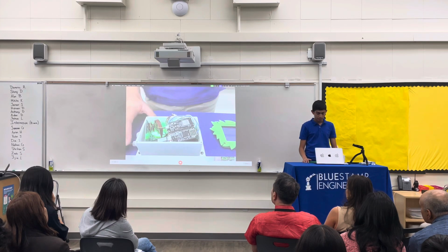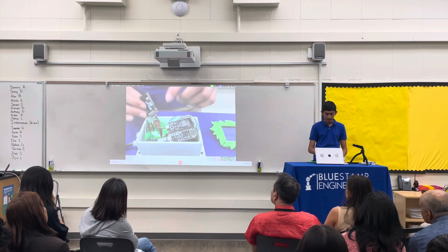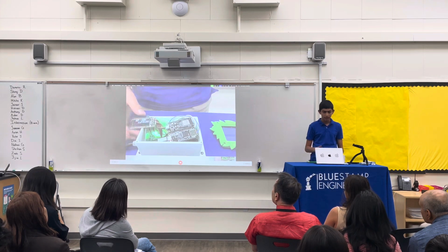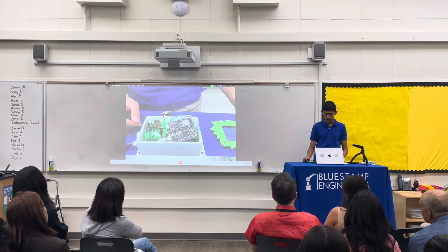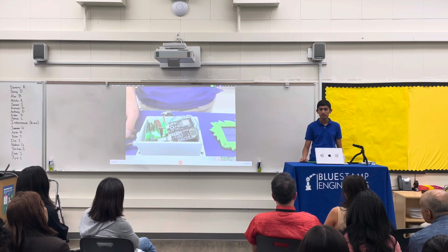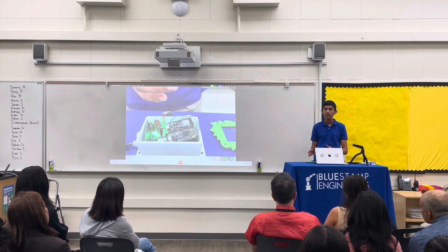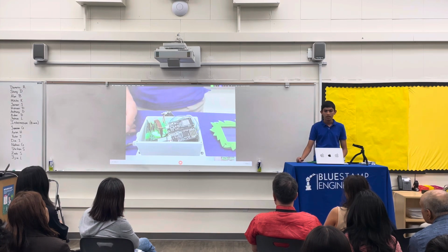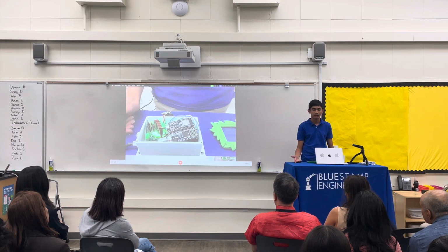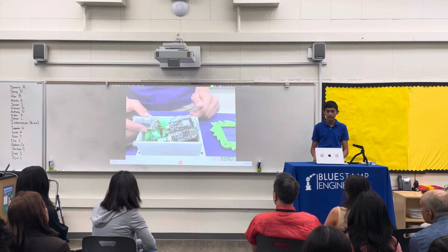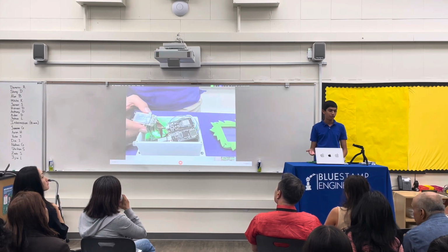So, the 2 modifications I made were the OLED screen and the LED. These modifications show the data right where the air quality monitor is. I chose to make these modifications so that I can see all of the data just from where I placed the air quality monitor, so I don't have to go directly online to find the data all the time. This is convenient because in case there is a Wi-Fi issue, the OLED screen and the LED will always be updated, whereas Adafruit.io might not update.